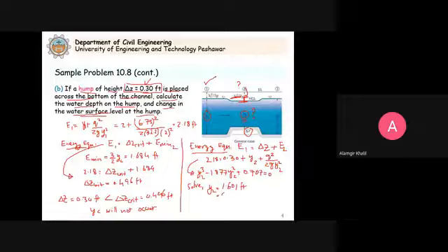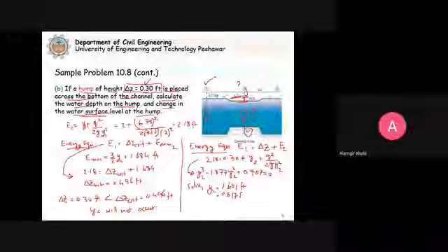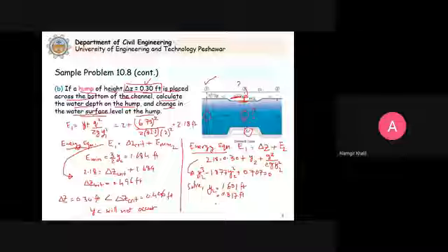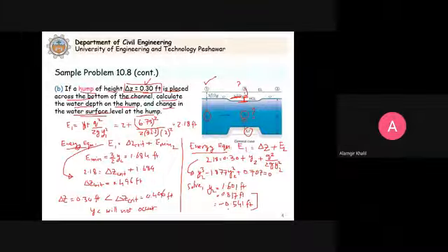Second one will be equal to 0.817 foot, and the third root will be negative, equal to minus 0.541 foot. So now this negative root is not possible, it is physically not possible. 0.817 is also not possible. Clear? These two are not possible. Why? Because 0.817 is a supercritical depth.